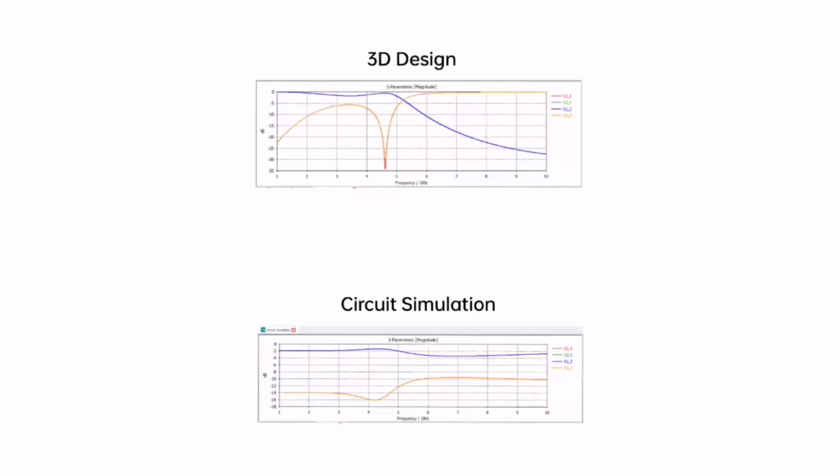So as we can see, it has been proposed and realized on a copper dielectric at 5 GHz Butterworth low-pass filter employing open circuit stubs, which has been tested. By altering the length of the stub, the open circuit stub filter also allows for simple adjustment of the stop band performance of the filter. The design of microstrip low-pass LC filters using slot ground structure has been investigated. The measurement shows the signal almost completely passes, using copper as the dielectric, resulting in a circuit that is ideal and passes the majority of the signal at the desired frequency, while the structure is maximally flat and produces the least amount of insertion loss.